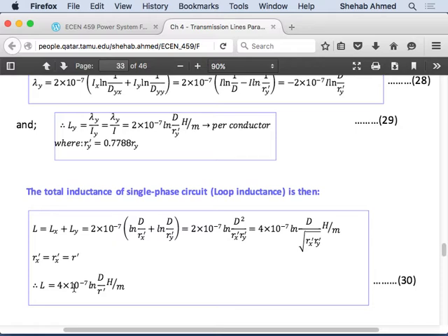So this is another example of three-phase versus single-phase transmission. Besides what we talked about originally, where we are reducing the copper needed to transmit a certain amount of power, the inductance of transmitting power in a three-phase system is half of the single-phase system. Which means that I require less reactive power supplied by the generator to feed a load if I'm supplying the load in three-phase.